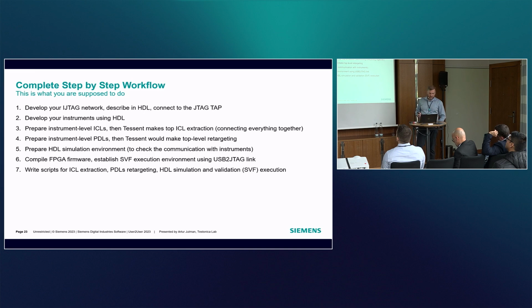You need to prepare an HDL simulation environment to check communication with instruments, and compile the FPGA firmware. That's also needed beyond the standard workflow. Establish the SVF execution environment using a JTAG cable, and you need some external tool for running SVFs.